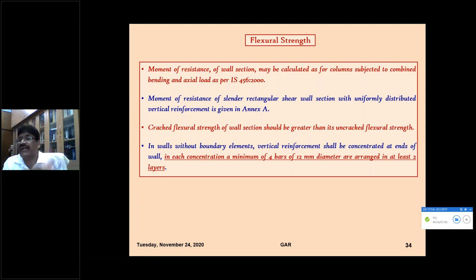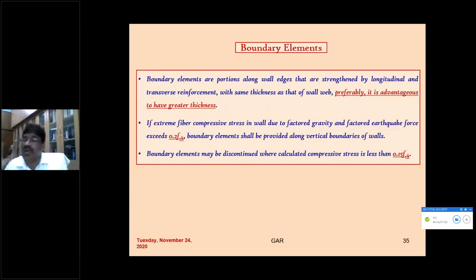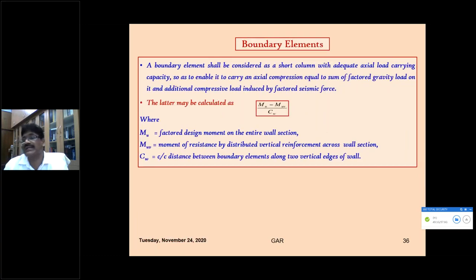They will act as special reinforced columns. The columns will attract a very high bending moment from the center of the wall. When you take the center of gravity of the columns on either end, these two will act as tension and compression members, and they have very high bending moment capacity. Now, boundary elements are special elements added to the shear wall to increase the stiffness and also the lateral load carrying capacity. Therefore, either you can increase the thickness or you can provide additional reinforcement. Either way, these end members or boundary elements give the shear wall very high capacity.